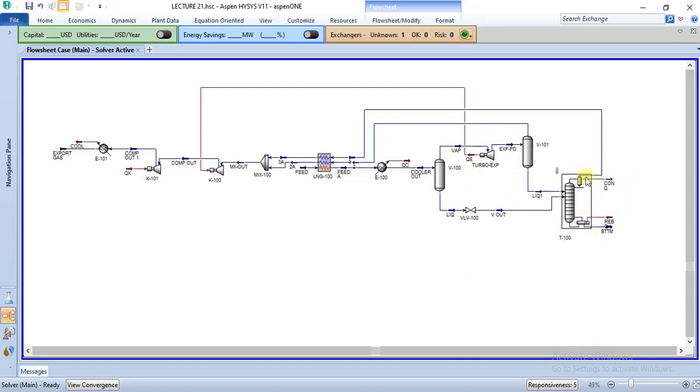So that the vapor present in them can be separated from the liquid bottom products, right? Then all these vapor outlets, the vapor outlet of the two-phase separator and the vapor outlet of the distillation column is sent back to the LNG exchanger for heat exchange, right?